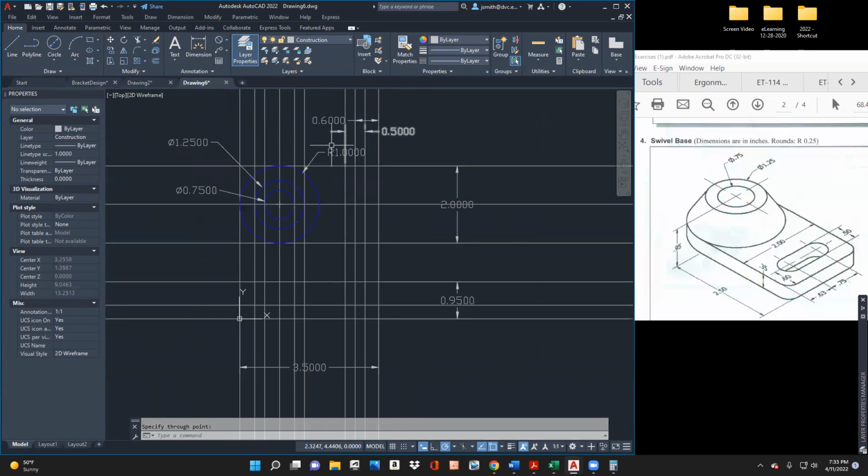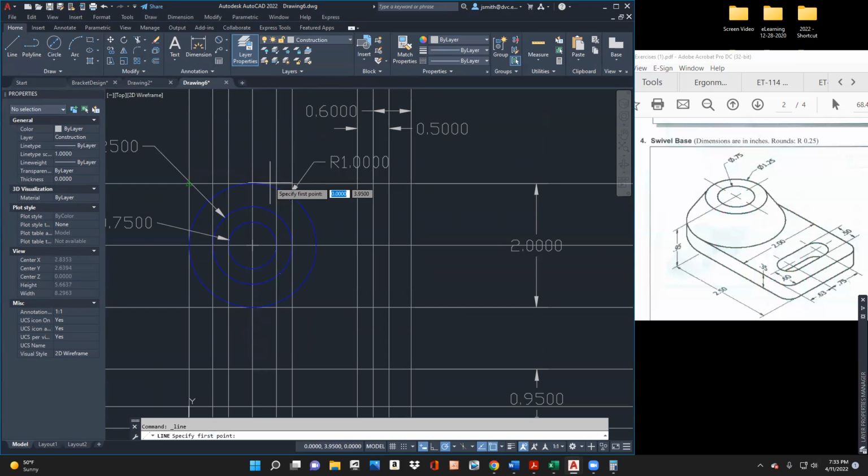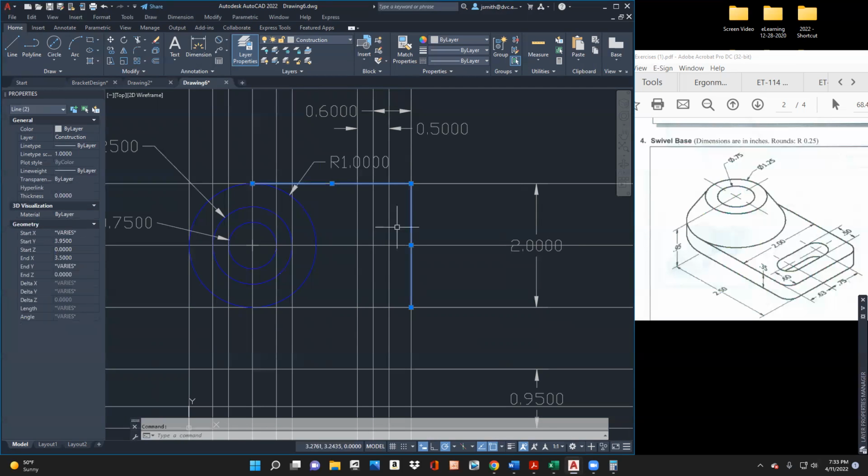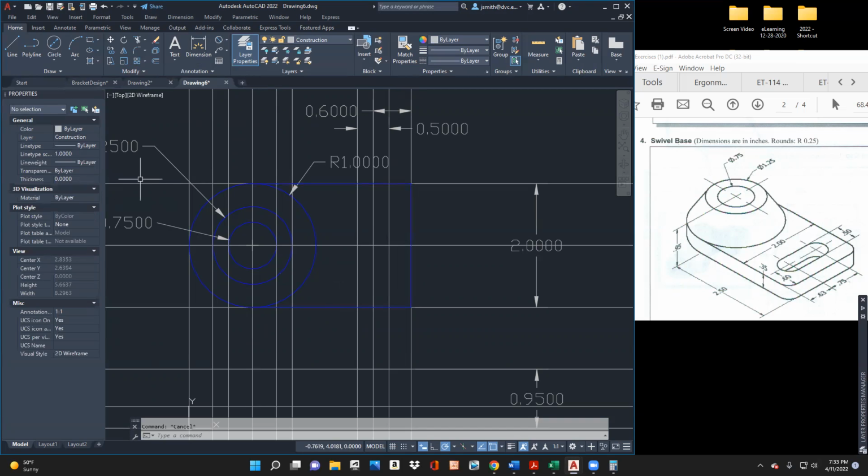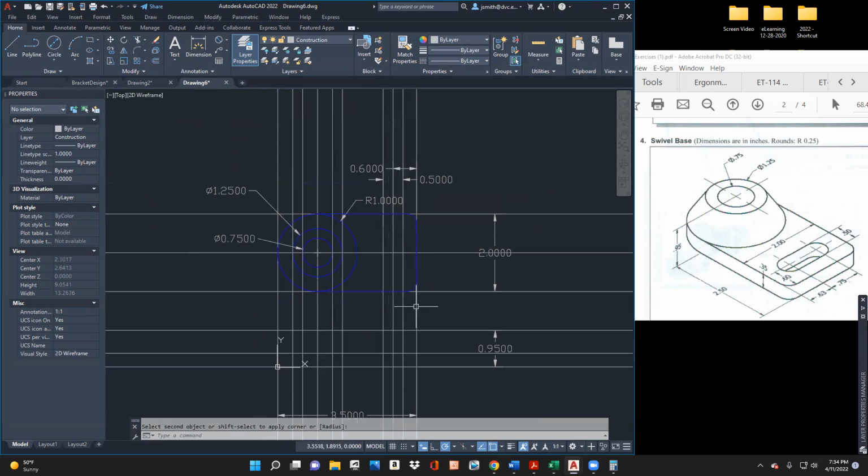All right, so now I'm going to start building this out here. Again, you could go ahead and just get in the layer you want to get into here. So 2.5. And so, for example, what I'm saying I would do is just go ahead and I've got these parts here. I'm going to go ahead very quickly and throw them into my, this is a little faster way of doing it. I'll type in fillet, and it told me that the radius is 0.25. Hit enter again. All right, looks good.